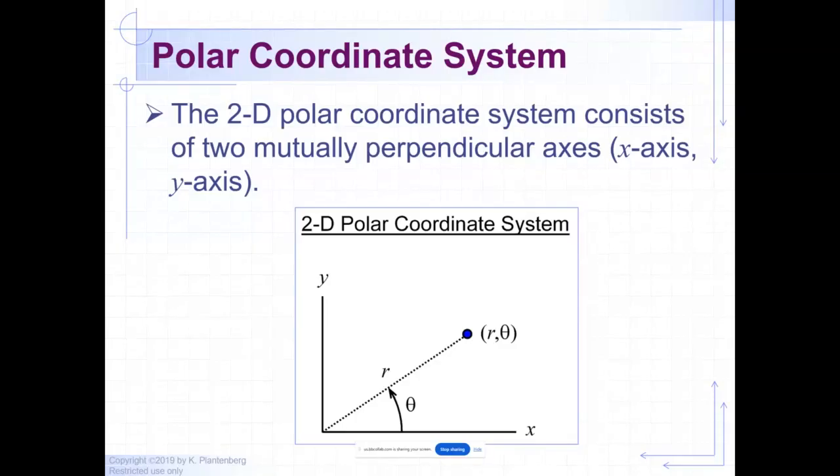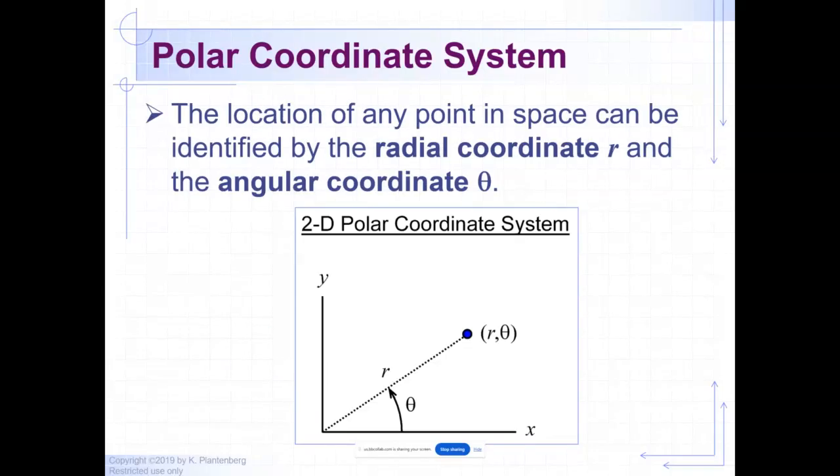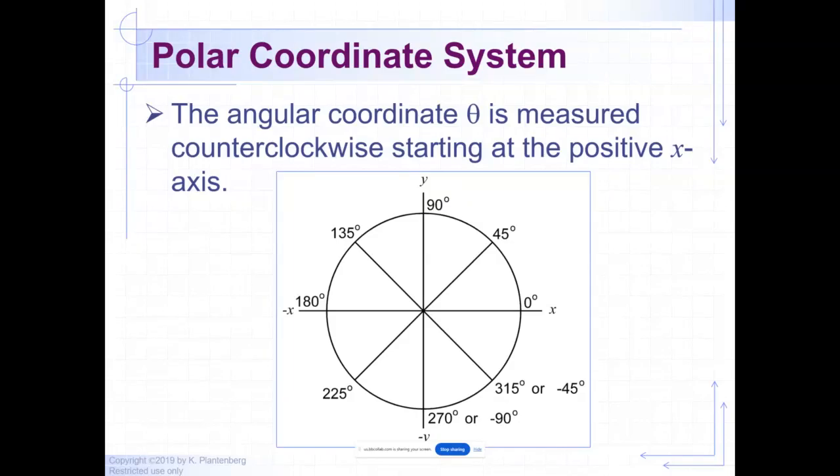And you're like, okay, well, how are the angles set up in AutoCAD? Well, I'll let you know. So let me see, do they have it on here somewhere maybe? There we go. So AutoCAD is set up with 0 as east, to your right. 90 degrees is north, 180 degrees is west, and 270 is south, if you want to think of it like compass directions.